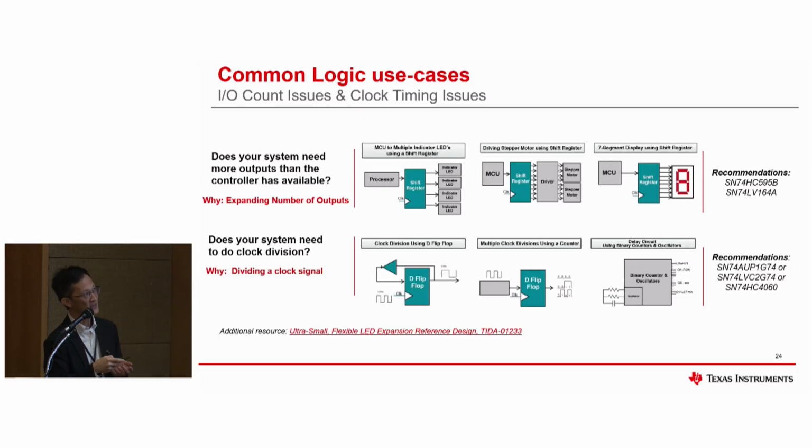And likewise, if you need to do some clock division, right? You can actually make use of a D flip-flop to do either a clock division or multiple clock division. So this can be easily achieved by using a very simple D flip-flop.